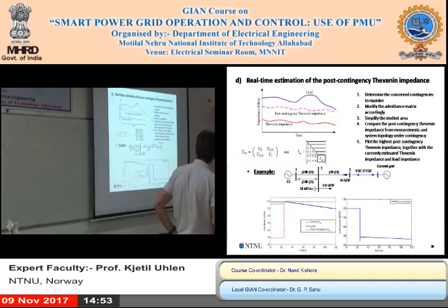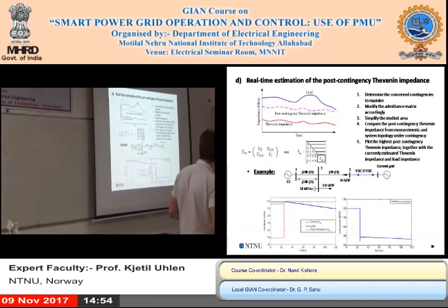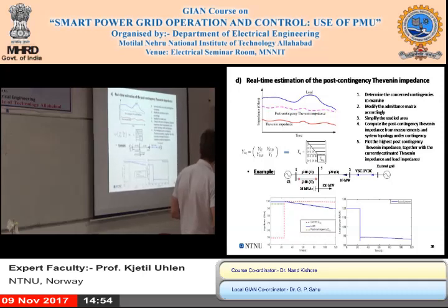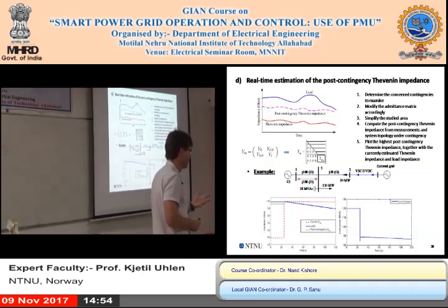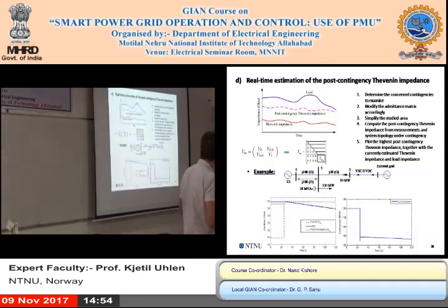This one doesn't count because it's a current injection. And that is also a point here: if you know that you are at some kind of limit, or if your feeder is controlled by power electronics, for example, the idea of Thevenin impedance fails, because you're in a nonlinear system. You don't know the response to that. So we better consider it as a constant current injection.